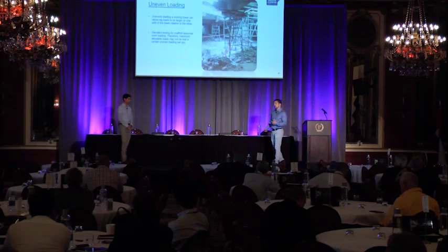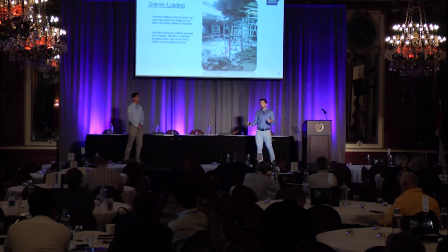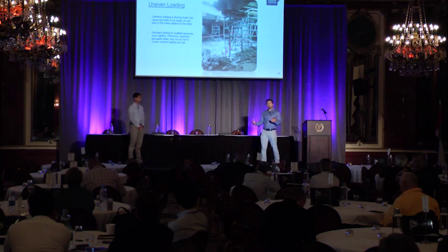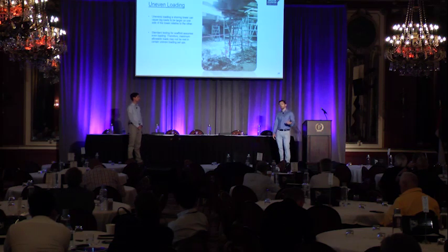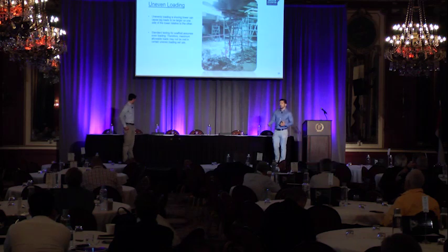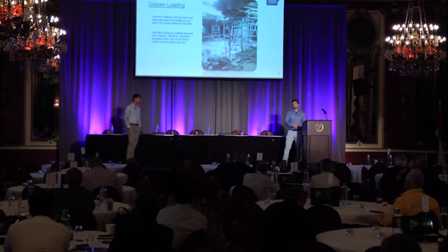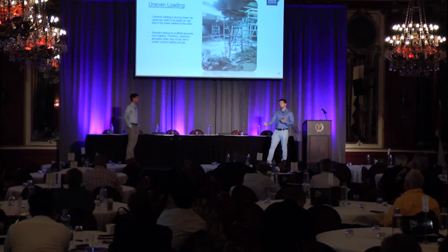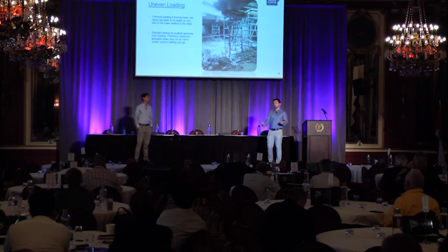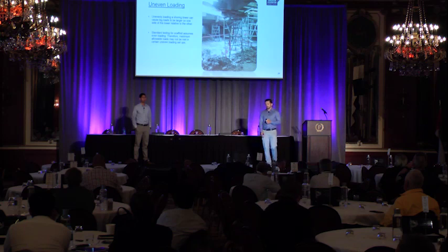So just being aware of where the towers are going to be and if there's any field obstructions up front, and if something does force you guys to shift the support beams, do your best to install the tower as centered as possible. In some cases, if the loads are light, it's not going to be that big of a deal. However, definitely want to reach out to your engineer to make sure you let him know, hey, we're out in the field, something was in the way, so we had to shift the tower and the beams. Just a critical item, this typically comes up during the actual installation of the project. And so just being upfront with your client, and so everyone's on the same page with what needs to be done.